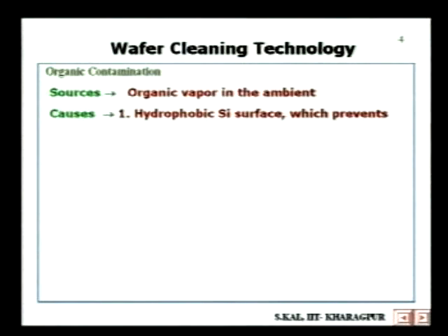The cause of these organic contaminations is a hydrophobic silicon surface, and at this juncture I should clarify what is meant by a hydrophobic silicon surface. Silicon by itself is hydrophobic in nature, but silicon dioxide is hydrophilic in nature.